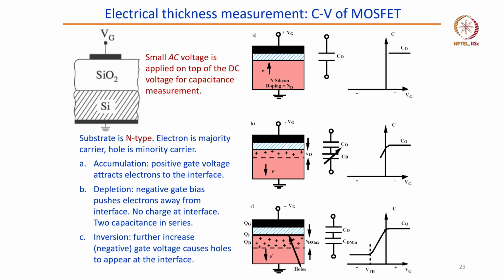So, there are different ways by which we can measure the silicon dioxide. This is a capacitance voltage measurement of a MOSFET. From that we know the thickness of silicon dioxide on the silicon. But like I said, there is the ellipsometer, there can be just visual measurement, and there can be an optical profilometer, which is using the stylus or diamond coating.